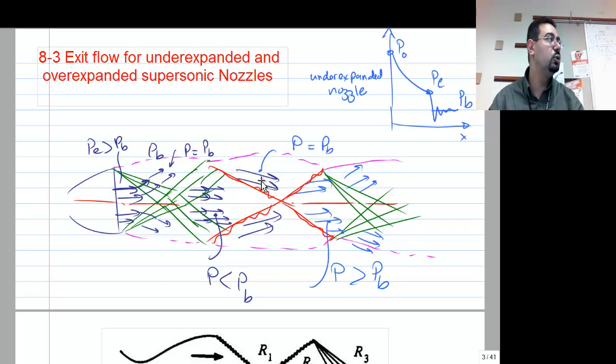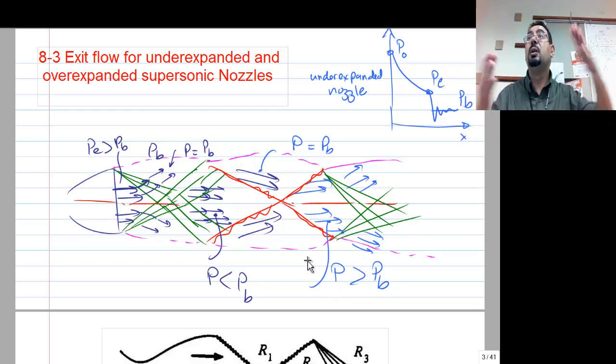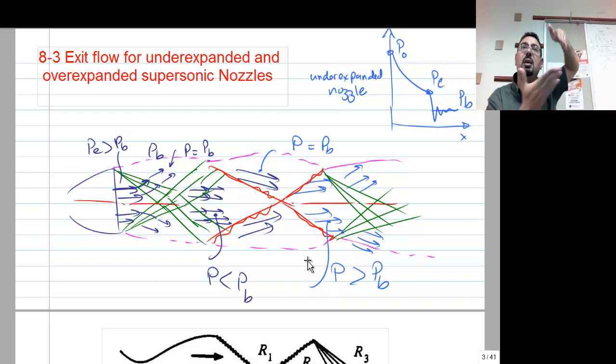So how does a supersonic flow going inward straighten up? By oblique shock wave. See, it's as if you are pushing it into itself. That basically increases pressure. So it straightened up by an oblique shock wave, which, what does it do? It increases pressure. So now its pressure is higher than P back. After it was at the right pressure but wrong direction, now it's with the right direction, but wrong pressure, a little bit higher.